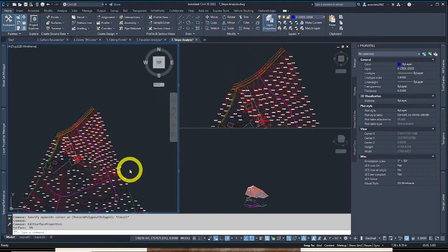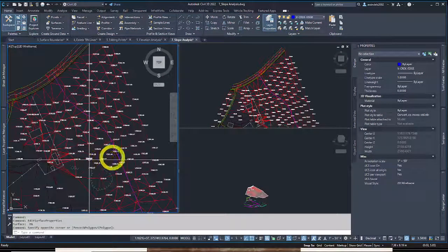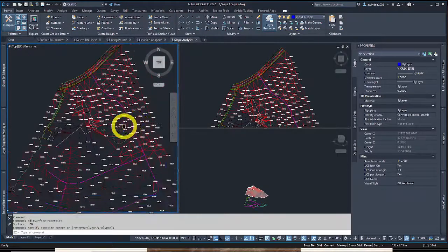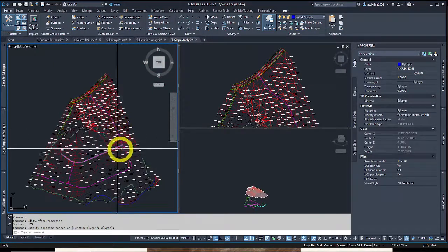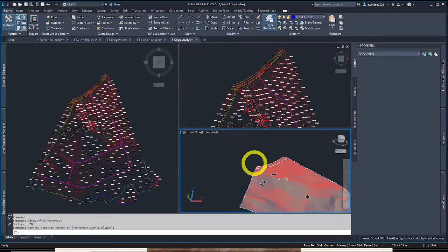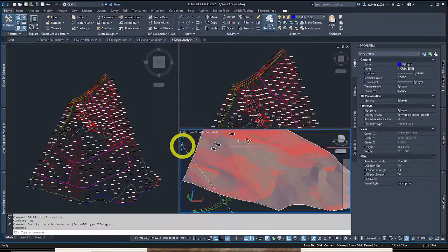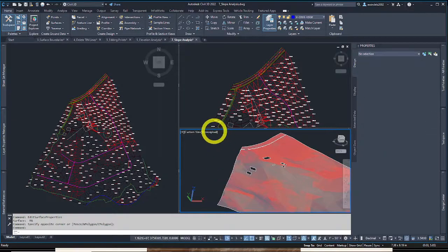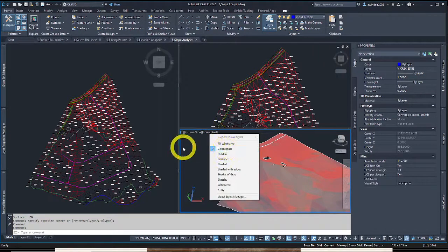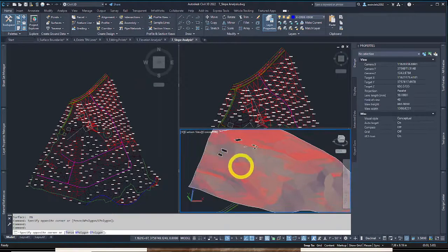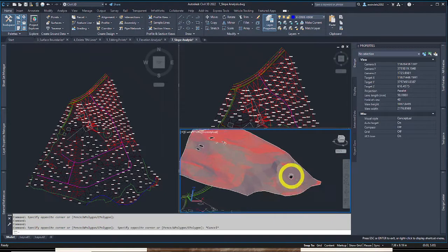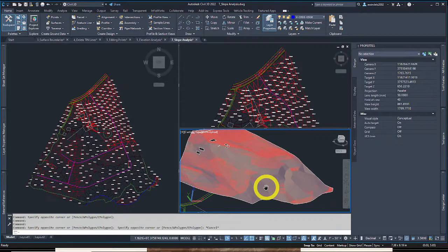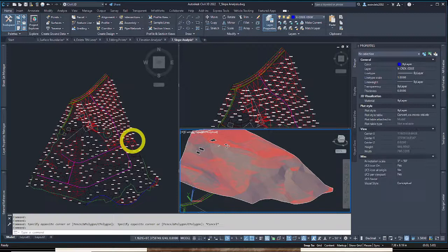And you can see the style populating. And it shows where the different colors are. This is where the steepest slope is, and that Dante's Inferno there. You can also see it in this 3D custom conceptual. Let's move it out a little bit. Conceptual rendering style. You can better see the analysis where the dark is where very likely this is over 8% plus ish, or that 7.5%. That's your not as buildable areas. That's basically the slope analysis.